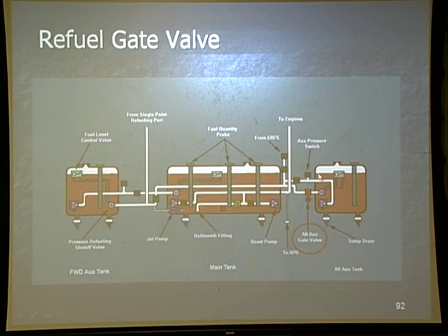Everybody see that? So if this valve doesn't close, I'd rather have it remain closed than remain open, because at least the fuel for the flying portion is usable. If the valve doesn't open for refueling, can I still fill that tank? Yes, but it just means I have to gravity refuel it. But I can still use it if I need it. Any questions about that?